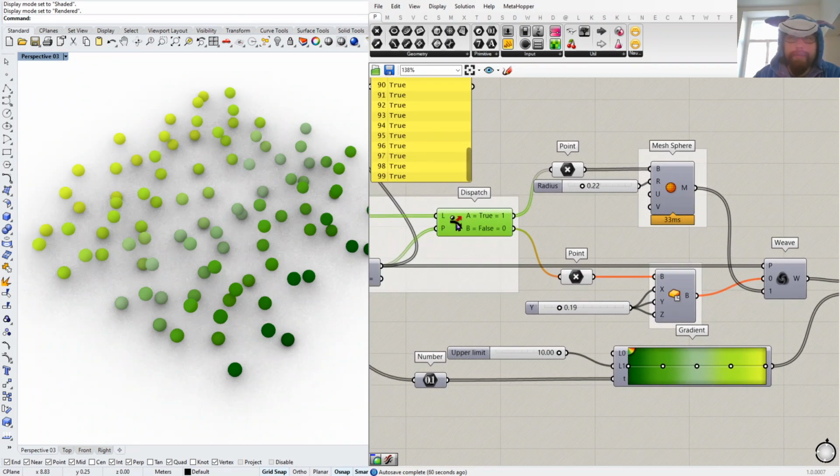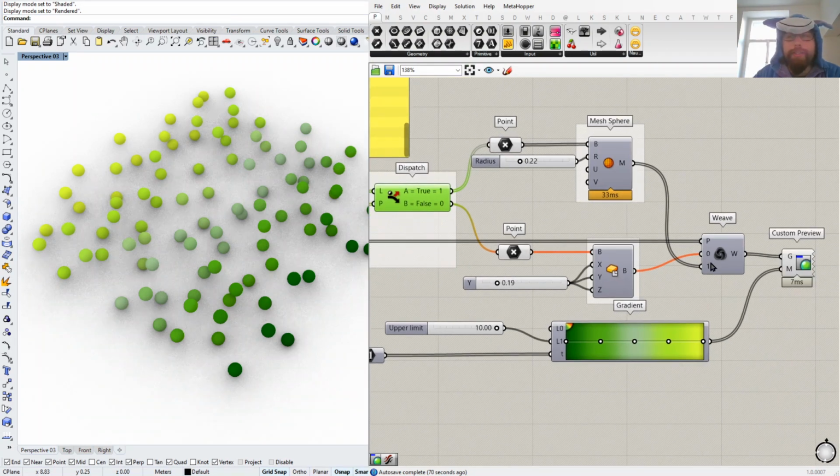And sometimes there's no other way than just to ask Grasshopper, like, are all these panels bigger than something? The area is bigger than something? And if yes, we have to maybe subdivide them because they are too big or something like that. And then you need to get the data back into the right order using the weave component.